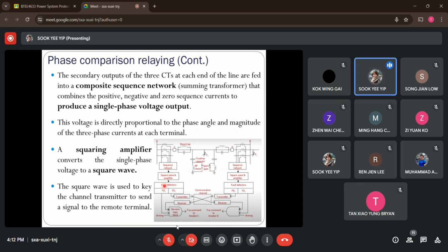All right, so depending on the fault detector, the fault detector here is actually the relay we use. Based on the local fault detectors, it will detect whether a fault occurs here, then it will send the input to the logic AND gate here. At the same time, we have another FD2, fault detector 2. So now you can see we have two relay cascades, right? The second relay here looks like the blocking relay.